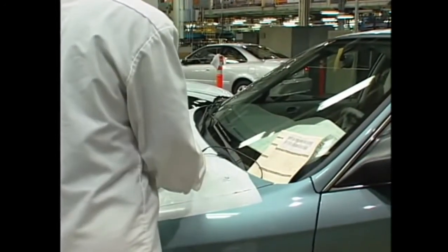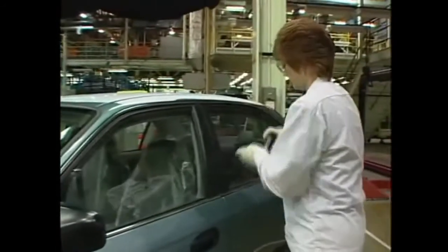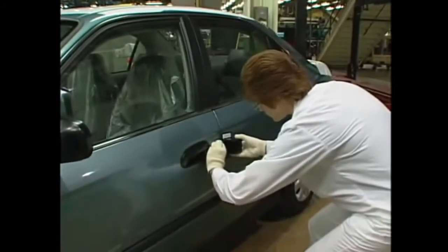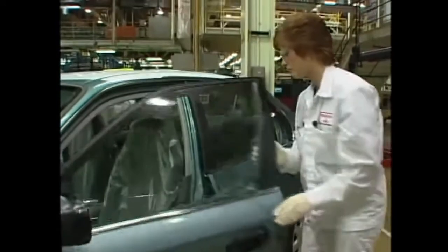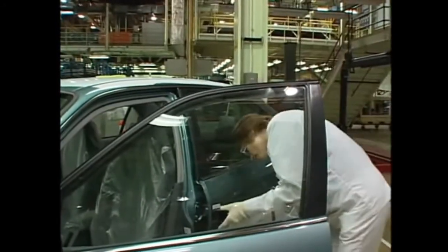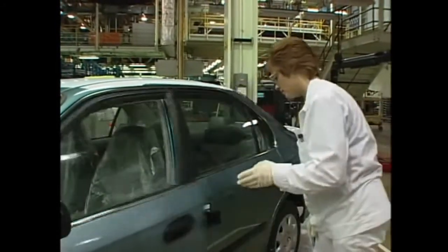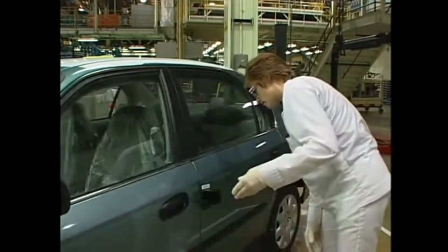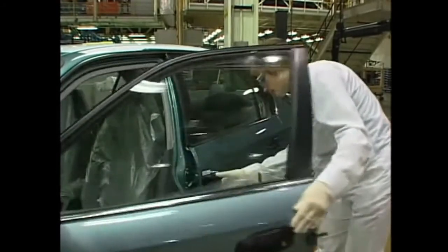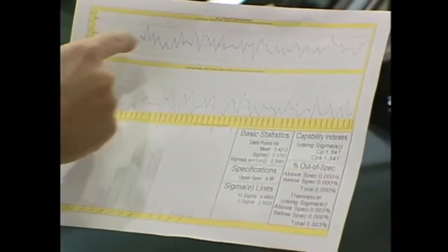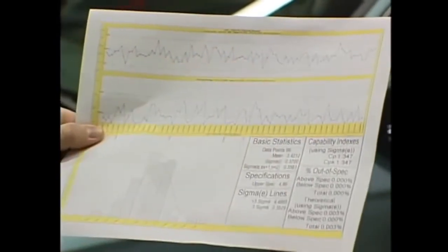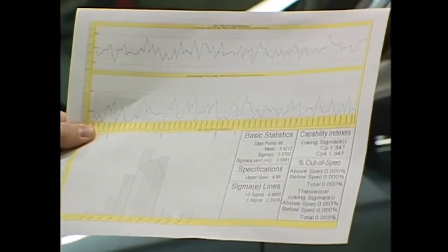The purpose of this test is to measure the amount of speed that it takes to close a door based on the customer's perceptions. In this test, a sensor is attached to the rear door and an interrupter is attached to the driver's door. Repetitive readings are taken of the closing door. Once this data is collected, it is put into a computer and a statistical software package is used to analyse the data. SPC control charts are used to analyse this data.